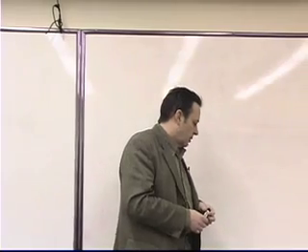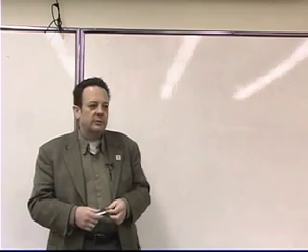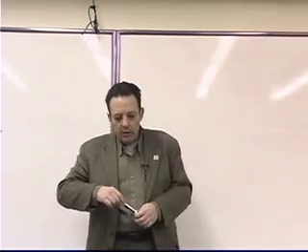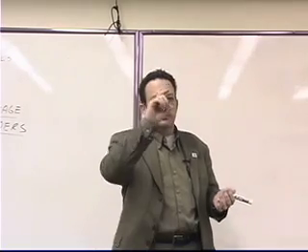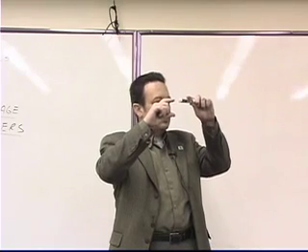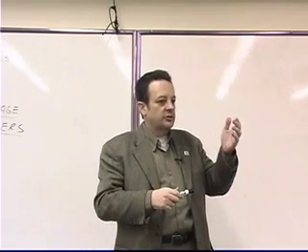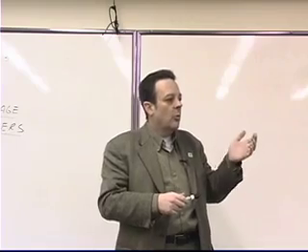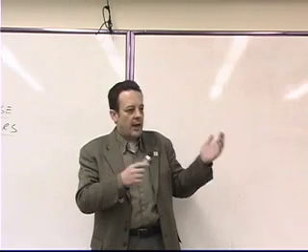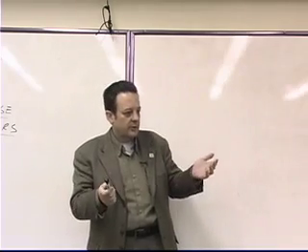There are carbon composite resistors. Carbon composite resistors just refers to the material that the resistor is made out of. There are fixed value resistors, in other words, resistors that are typically coated with a particular color scheme that lets you know what the value of the resistor should be and also what the tolerance of the resistor should be. In other words, tolerance, accuracy, is it plus or minus 20%, 10%, 1%, 5%, okay?